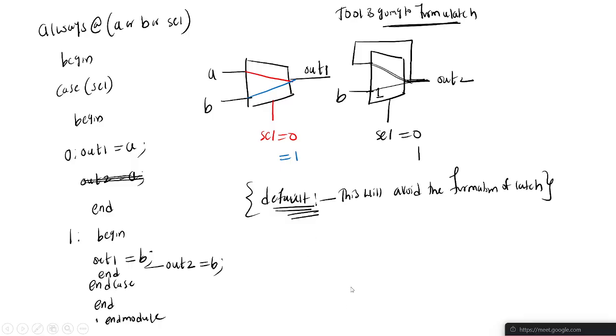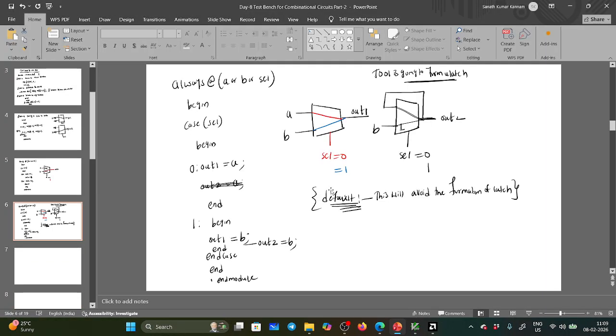Okay, so this is also one important interview question. Why are you using the default statement in the case statement? In order to avoid the formation of latch, we are using the default statement. Is it fine? Did you understand? Shall I move forward?